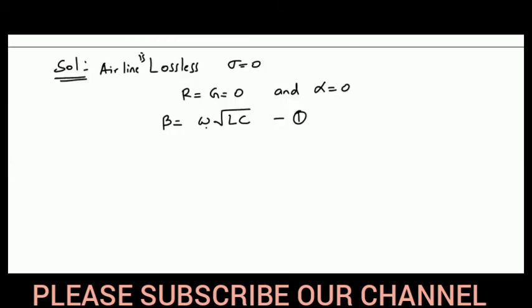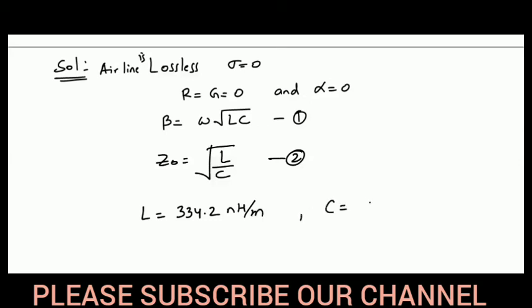In this equation, omega and beta are known to me. Similarly, Z0 is under root L by C. This is also known to me. This is the second equation. Now if you solve these two equations, you will get the value of L and C. So L comes out to be 334.2 nanohenry per meter, whereas C is 68.2 picofarad per meter.